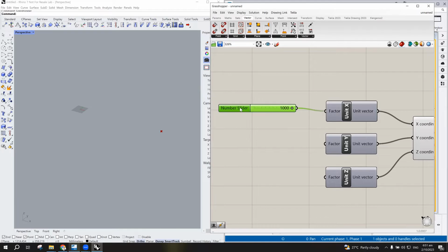Okay. All right. Another thing is the slider shortcut, if you don't want to type here like earlier, I type here slider, right? And then number slider. Actually, if you double click the canvas and then you just simply type, let's say 0, two dots, and then you type here 1,000, enter. So it's the same. Yeah. So that one is the shortcut.